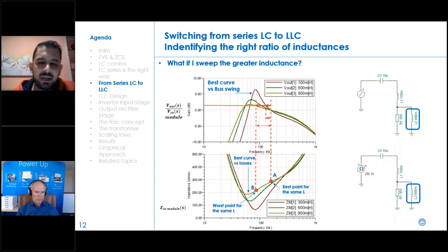So concerning the magnetics, if we assume the change in the flux density is balanced by the change in frequency when we move from the point A to point B or vice versa, then the core losses stay the same, let's say approximately the same. And the A point continues to be the best because of its higher impedance.